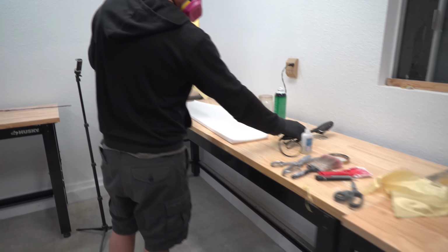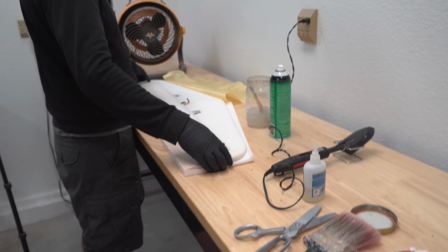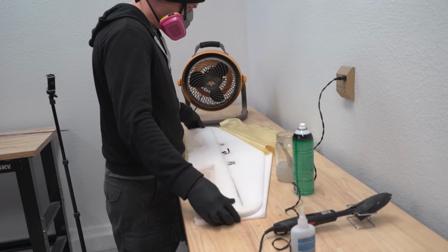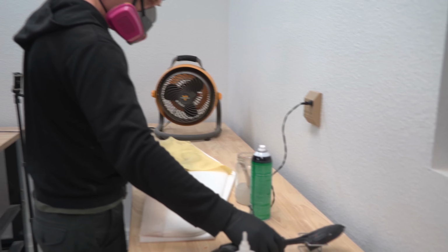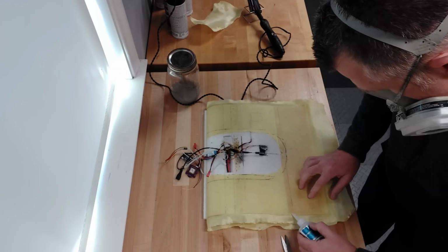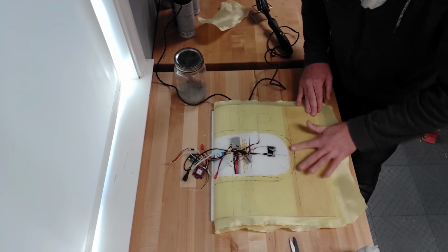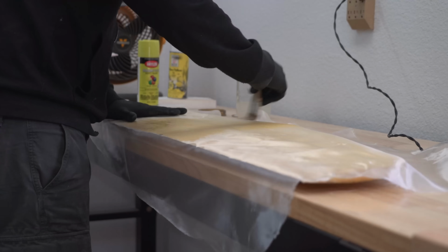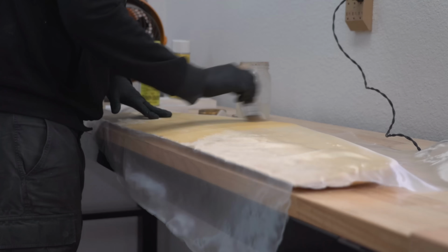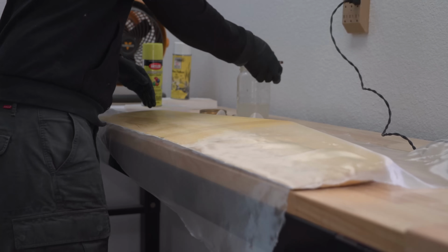The fabric is attached to the wing with goop thinned in propyl acetate. An iron set to 130 degrees Celsius is used to evaporate the solvent and remove excess adhesive while adhering the fabric to the core. This process does not work well without the iron. Super thin CA is used to attach the Kevlar to the balsa portion of the wing. The goop mixture is insufficient for this task. A veil of 0.75 ounce fiberglass goes over the Kevlar with the goop and propyl acetate mixture. This allows for a much nicer finish on the aircraft later.